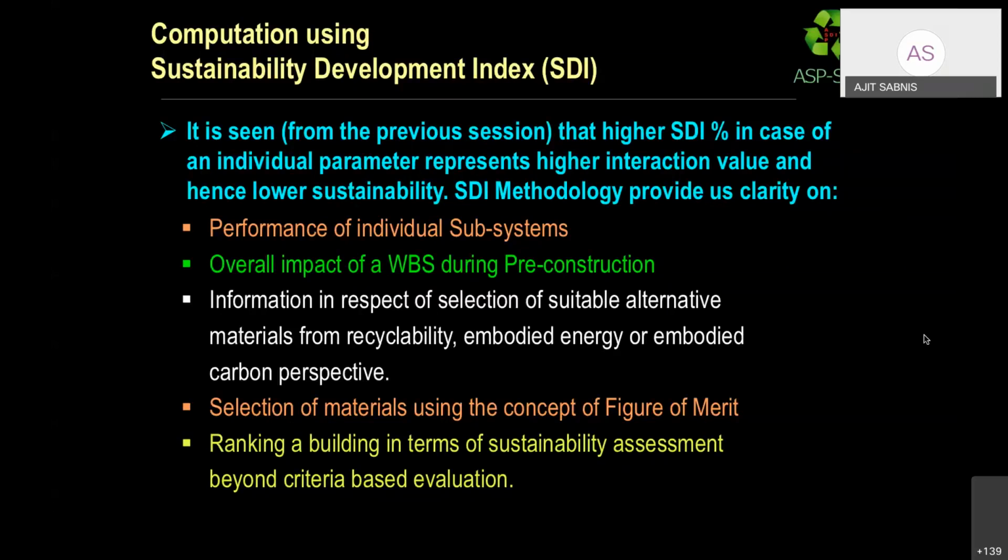So the SDI methodology provides us clarity on the performance of individual subsystems, the overall impact of the whole building system during the pre-construction phase, information on the selection of suitable alternative materials from recyclability, embodied energy and embodied carbon perspectives, selection of materials using the concept of figure of merit, and ranking the building in terms of sustainability assessment beyond criteria-based evaluation. So these are the primary advantages of using geo-specific or climate-specific sustainability development indices.